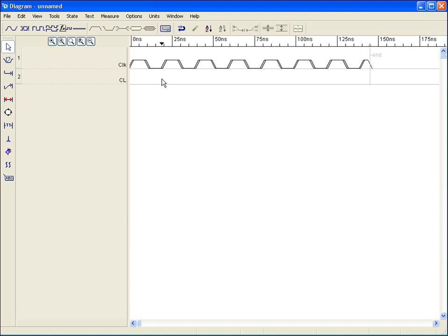Simply point and click the area where you wish to place an edge state transition, and TimingDesigner will automatically draw the signal to that point, toggling between a high and low state with each mouse click. You can easily change the next toggle state by selecting the desired next state button before placing the next edge. The last two successive state values used for the signal will be current toggle states. The end marker is a termination point for the diagram, so any click to its right will terminate that particular waveform.